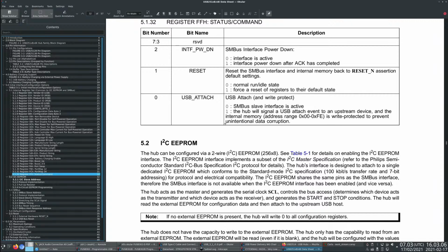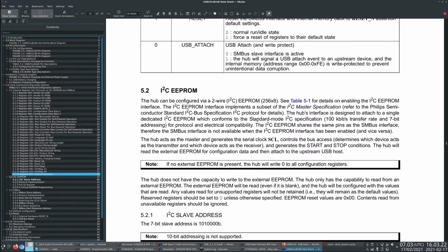The only question is that in that case, we couldn't trigger DFU mode if the STM32 messes up the hub config. Yeah, this needs testing. It's a little bit tricky.